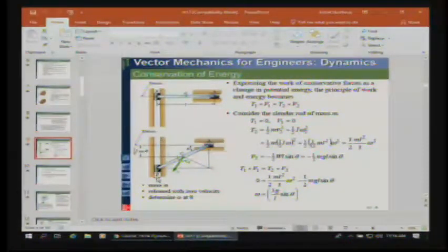If B drops in elevation, its potential energy decreases. So the potential energy of A stays the same, but we have a kinetic energy of A when it's moving at time 2 and a kinetic energy of B as it moves at time 2. So when we set that up, we can say 0 is equal to the kinetic energy at T2 and the potential energy at T2, and we can solve for this omega based on that idea.